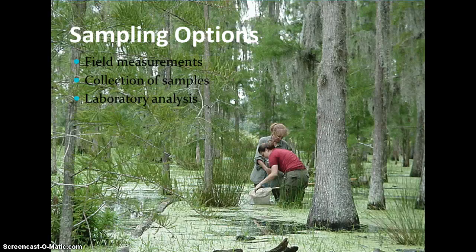Parameters can be tested in the field using single or multi-parameter meters or test strips. Water samples may be collected and tested on-site using instruments, color wheels, or other equipment. Water samples may also be collected, preserved, and delivered to laboratory facilities for further analysis.